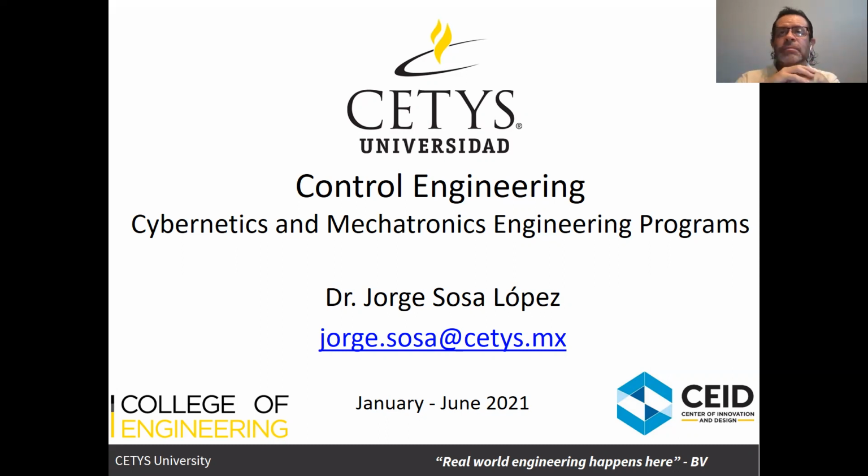Once I do that, then I can create and connect different models of systems to create other systems, larger systems, feedback systems, in which I can analyze how these systems behave with regards to their transient response, which means the moment where I input a new signal to the system or a new stimuli to the moment it stabilizes. I can also analyze stability of the system. I know that all of this is in the end related to the transfer function and the poles of the transfer functions and how these poles are located in the complex plane, in the S plane.